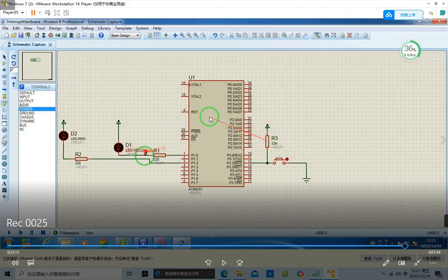If you place your device in a laboratory, or some other place, for example at home, where there is less interference, this resistor can be a bit larger. Because the smaller the resistor, the stronger the pull-up, and the interference will not be able to change its voltage level.